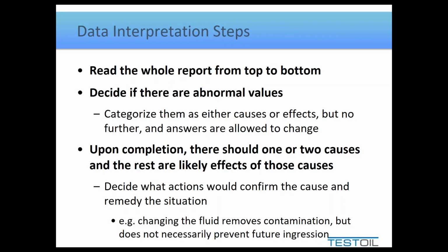Well, yes, the lab is supposed to offer their opinion, but you, the end user, might know a bit more about the circumstances around the lubrication of that component, around the maintenance activities. You know what impending turnarounds or shutdowns you might have. There's a lot more information in your head to properly interpret the report. So here are the steps as I see that you should go through to properly interpret the report and make sure you get the correlations where they exist and you avoid the ones when they don't exist.